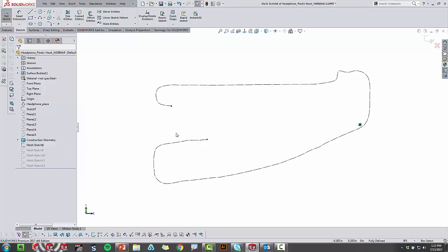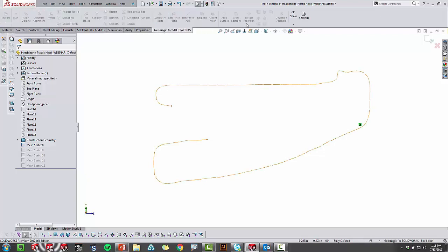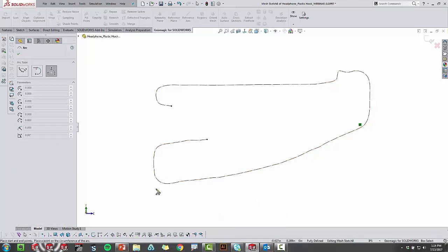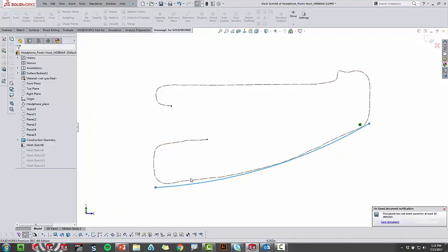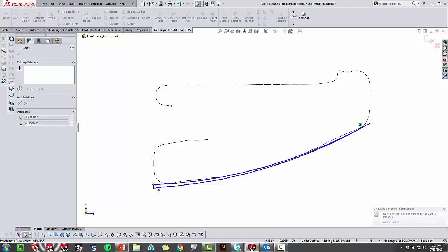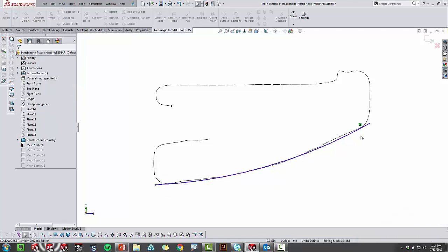I have this one sketch as a polyline, and that's because of the option we chose when we generated the cross section here with our tool. Right, so there are some imperfections here, so that's why I choose to have this as just construction geometry that I can trace over. So what I'll start doing is I'll start with a 3-point arc for the section here that is curved. I'm going to try to aim to the endpoints to what would be the virtual sharp. Once again, I don't have to be 100% precise. As long as it overlaps enough, I'm going to be fine with it.